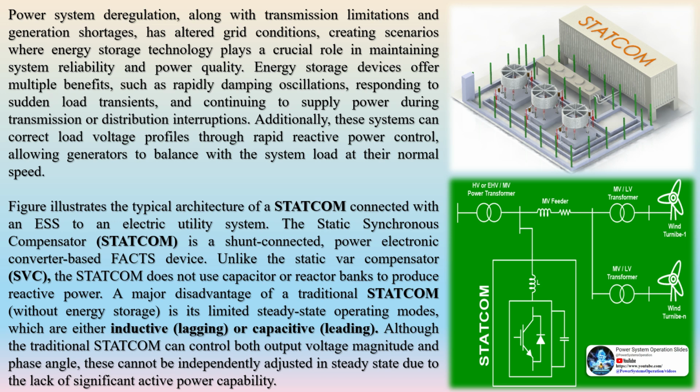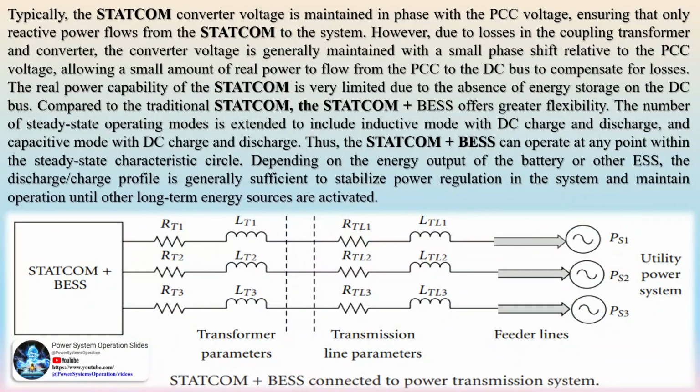The pulsating nature of wind turbine torque produces oscillatory active and reactive power outputs at blade passing frequencies, worsening power quality at the PCC and potentially damaging connected generators.